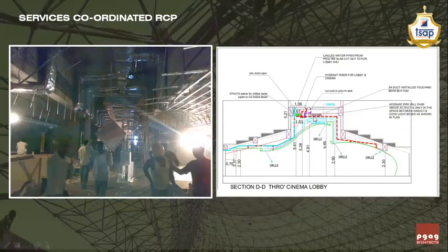The two services also, if they overlap with each other. For example, if the pipe is not laid the way we have shown, or you have not observed that you are supposed to show the HVAC duct line out, or the pipe line out the way you want it, then the two services will overlap with each other, and finally the false ceiling height of the space will come down, and it will be your fault that you have not executed it properly.